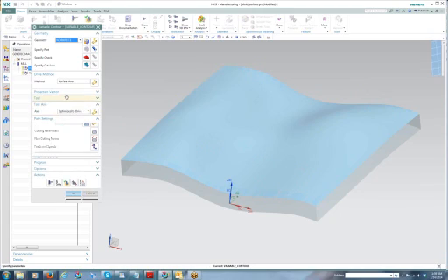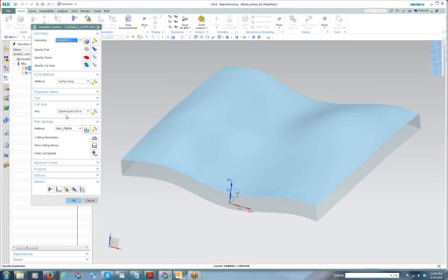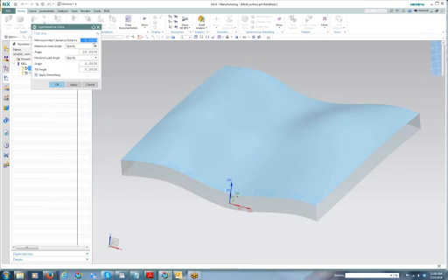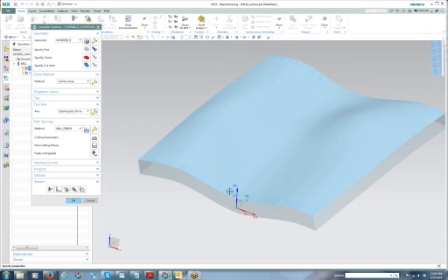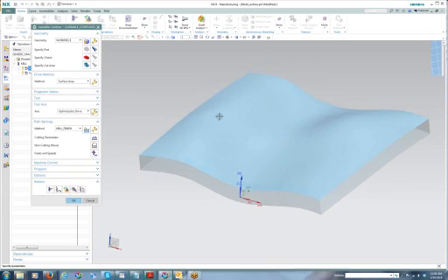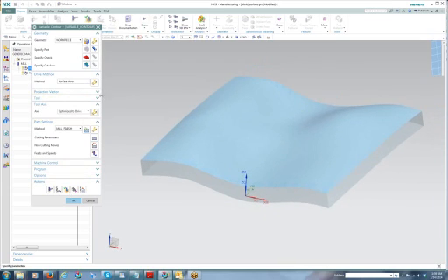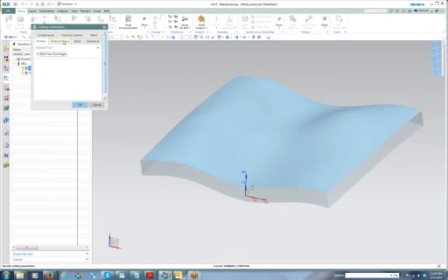We're going to change our tool axis algorithm to optimize to drive. Here in the settings, I've got a 7 thousandths heel clearance and a maximum lead angle of 25 degrees with a nominal lead angle of 6. What NX is going to do is look at that geometry and figure out automatically what the step over needs to be to provide the ultimate result that I'm looking for, the finish of the tool. Also, it's smart enough to look at the stock and only add passes where required. Here's where that's set up.